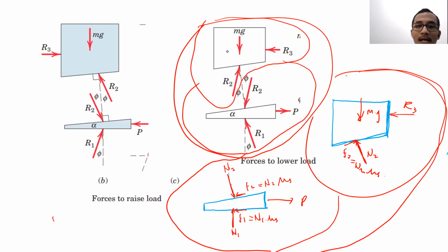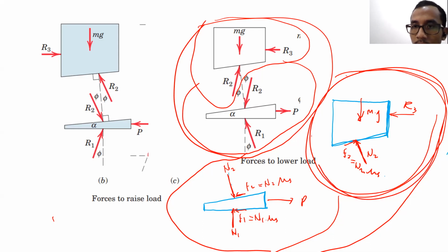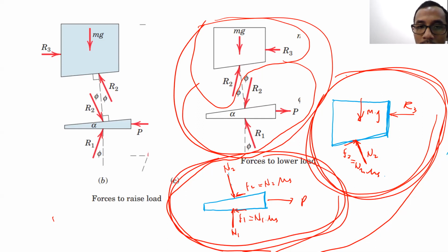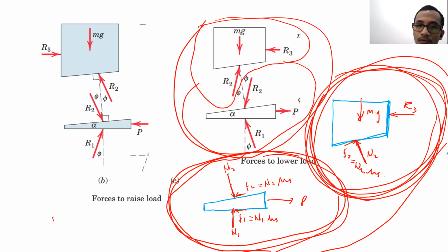I suggest you use this kind of way to draw the free body diagram, because by doing that, you know exactly the components of the forces, and it will be much safer for you to solve it this way, by separating the normal force and friction force.